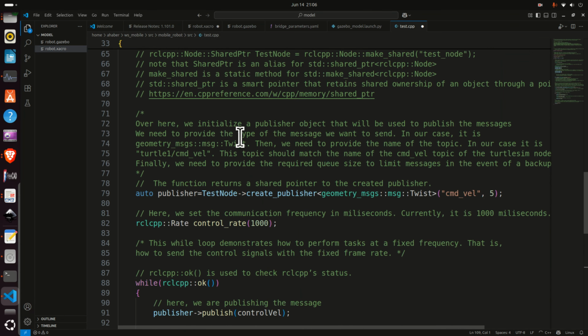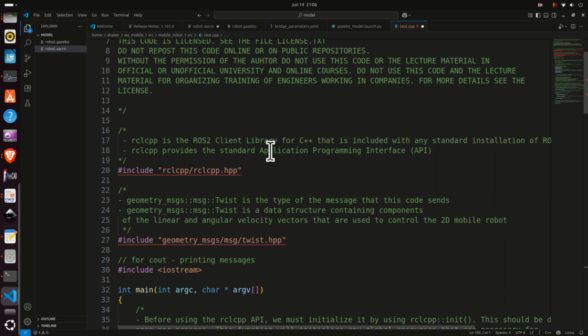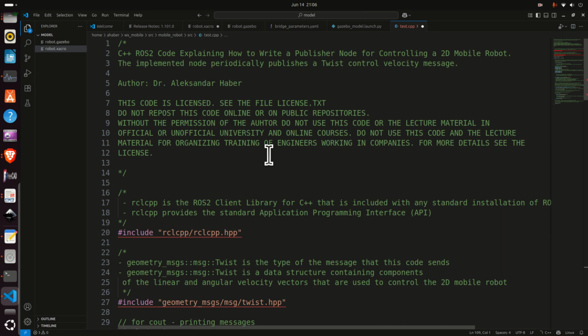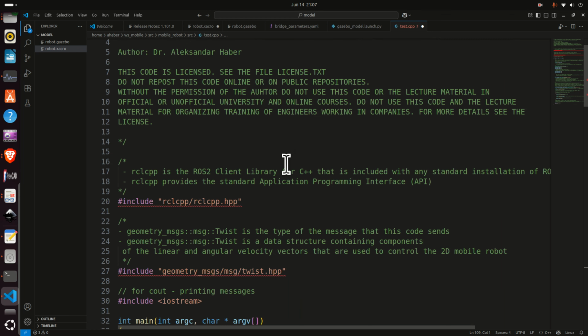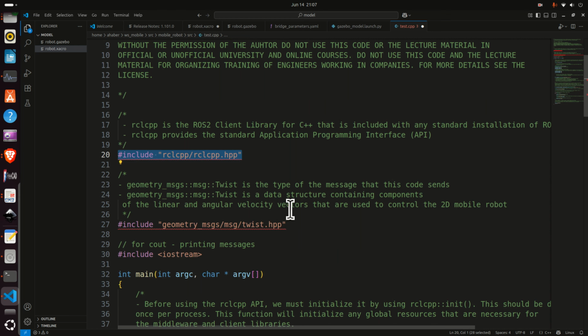On my YouTube channel, there is a separate video tutorial thoroughly explaining how to write C++ files for controlling ROS2 programs. Here, I'm going to briefly go over this file. First of all, whenever you want to use C++ inside of the ROS2 environment, you need to include rclcpp. rclcpp is the ROS2 client library for C++ that is included with any standard installation of ROS2. This library provides the standard application programming interface or API for controlling ROS2.